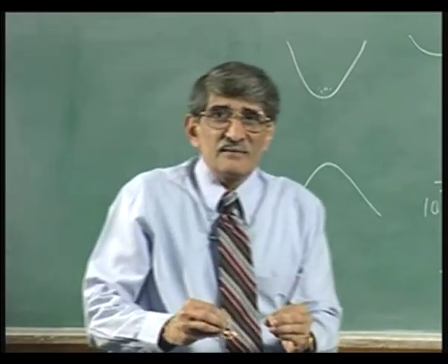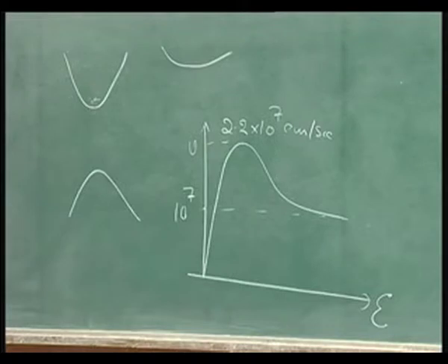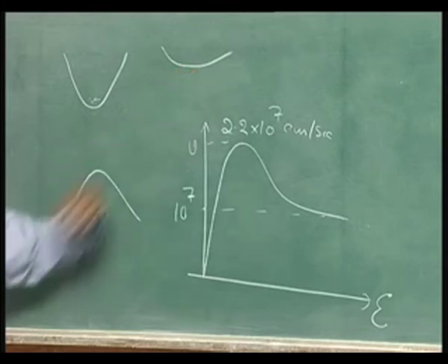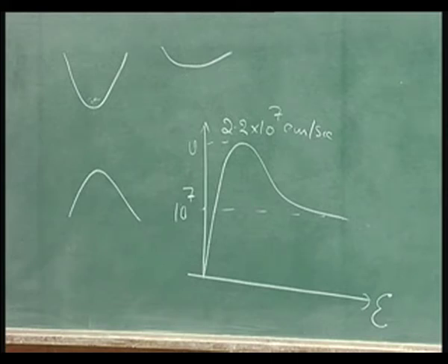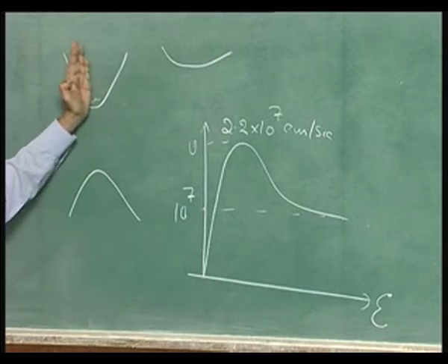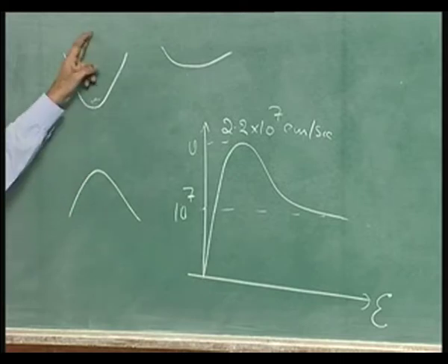To talk in more technical terms, you can view the entire difference as the difference in the relaxation times for energy and momentum. It takes some time to acquire that energy. Once it acquires the energy, it goes and settles to the momentum required to transfer from here to here. There is a momentum difference. Momentum is m into v, and half m v squared is energy. So, it has to acquire that energy. Once it goes to that energy, you have got the momentum. If you do not like to understand it that way, you can say that there is a finite time which lapses before the electron gets transferred from this valley to that valley, and during that finite time it is moving at a much higher velocity. So, it goes into a much higher velocity.